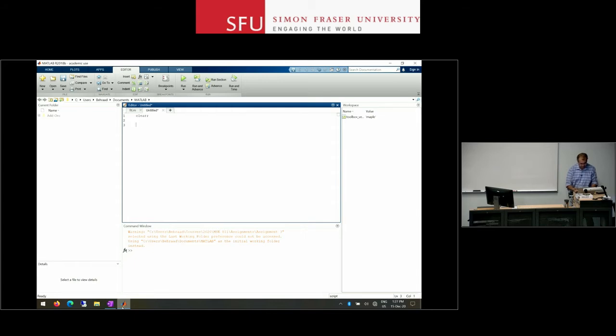VD is equal to N, that's 2, times 0.025 for room temperature operation, times the log, that's natural log in MATLAB, of ID that I assumed, so 2 milliamps, divided by IS of the device, which was 1 nanoamp. That's 1 to the minus 9. And I can calculate that. And then from that, I go and calculate the value for A. The parameter A that I had was 2.5K.